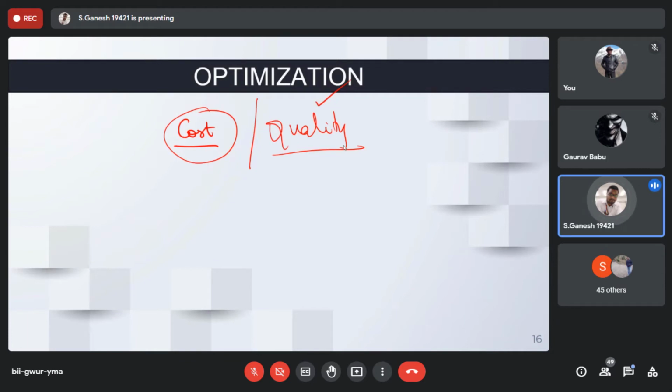Practice with different types of load patterns. You come to know that in a previous model I got a safe limit, so why not go to a second project with the same model? But the loads are different, so this size is not suitable for this particular load, and I redefine my size. So I come to know that for a certain set, this size is suitable for this particular range.